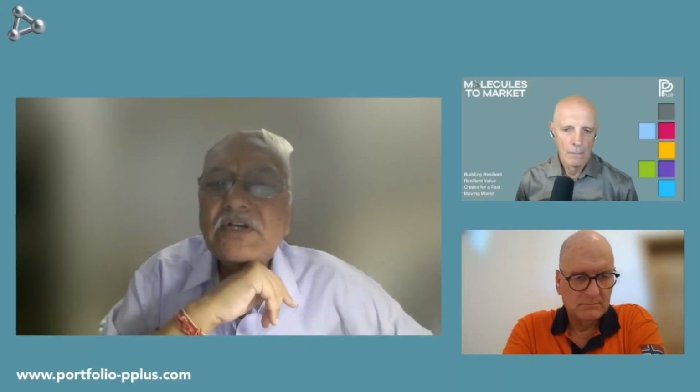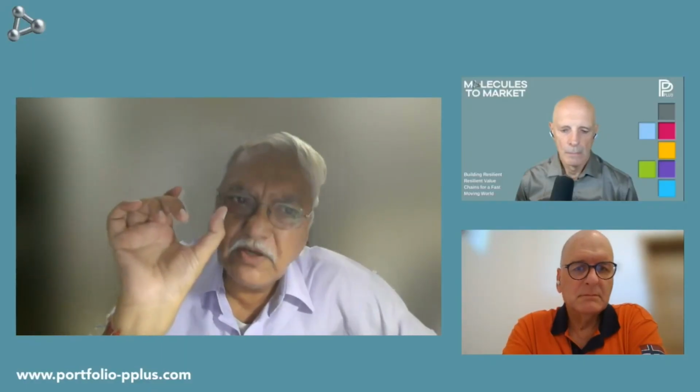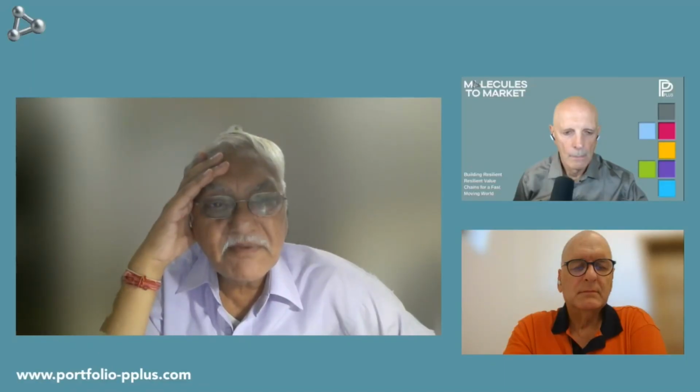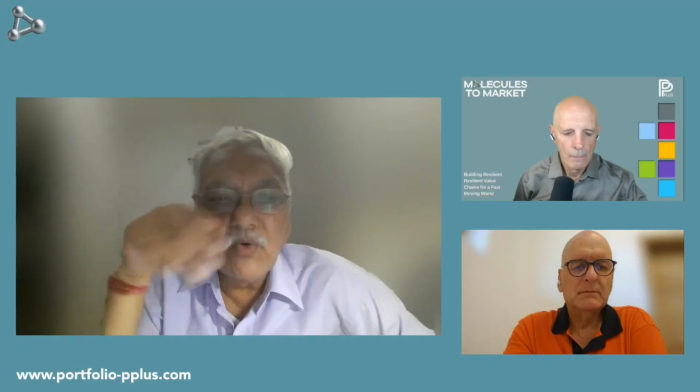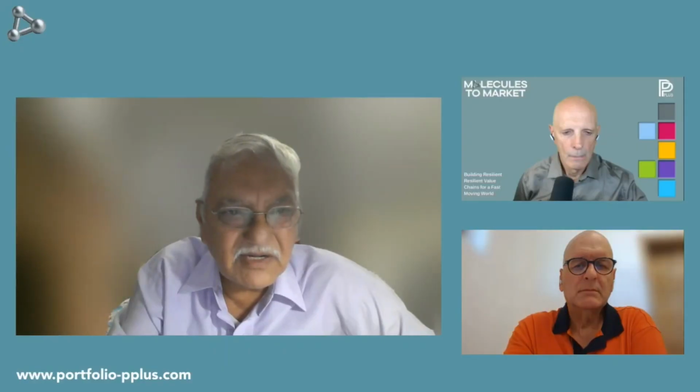What we tend to do is a little bit different, which I'm going to explain now. So the first document which we prepare is a feasibility report. And that is the first inception of the project. Apart from one parallel work which we are doing on the project, trying to finalize this configuration, optimize the material balances, suit it to the objective function of the plant, rationalize the capacities of the units, rationalize the overall utility requirements, finalize the interfaces, look into the environmental considerations. These are all technology-driven issues, which are project per se requirements.